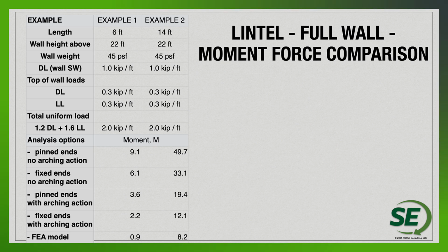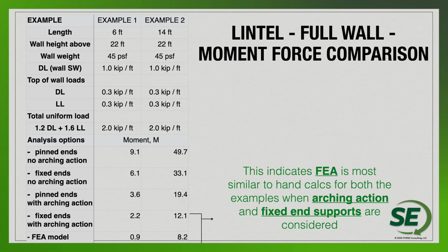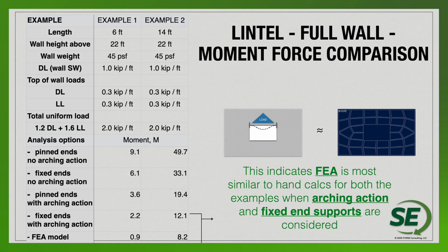We also can see the fixity, fixed end now being something that we can somewhat validate through our finite element analysis. Arching action with fixed ends correlates pretty well with what we're doing with finite element analysis. So you can see that that would be the most comparable solution.